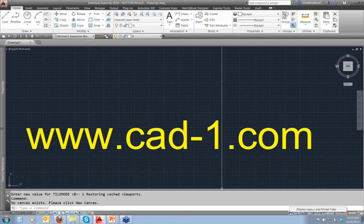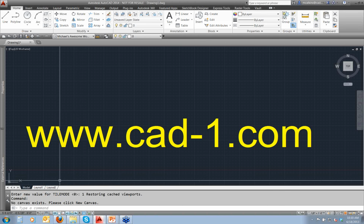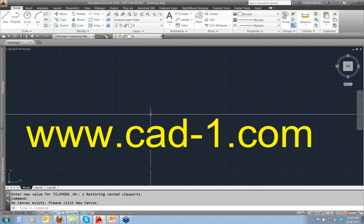So what you need to do is come down here and right-click on that little black icon and say Display Layout and Model Tabs. I'll also point that out because I taught something like 200-something AutoCAD students last year, and throughout that time, people here and there managed to accidentally close the layout tabs, and the quickest way to restore them is to right-click on that little black icon which appears. You notice that black icon no longer displays here. You can also do this through the Options dialog box. You can turn on your layout tabs.